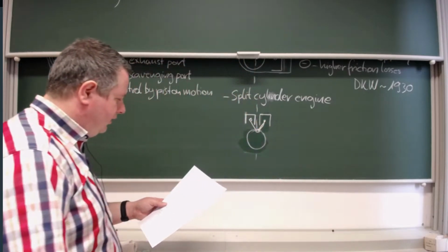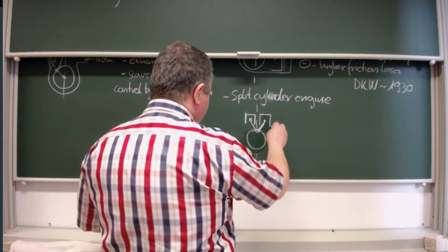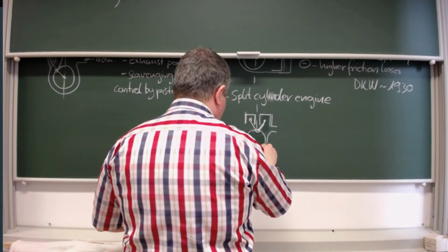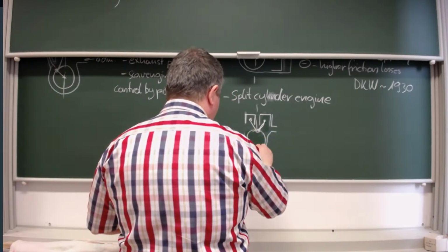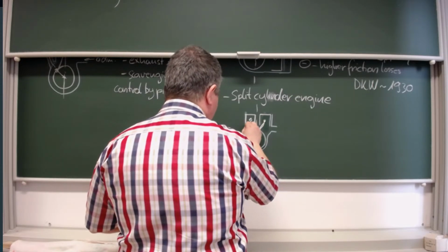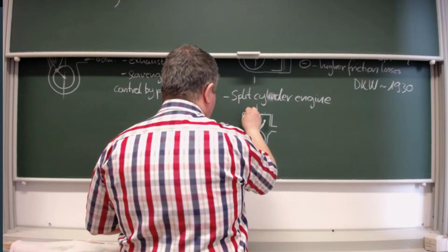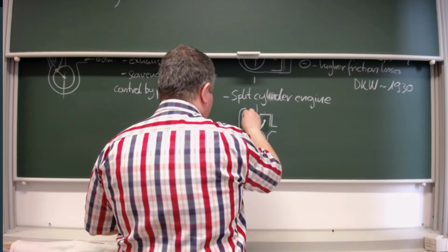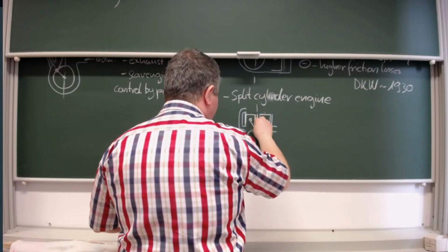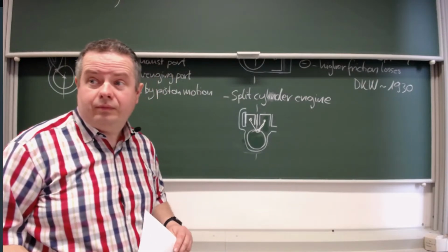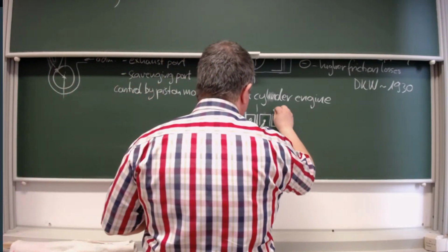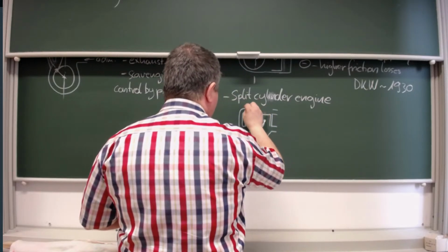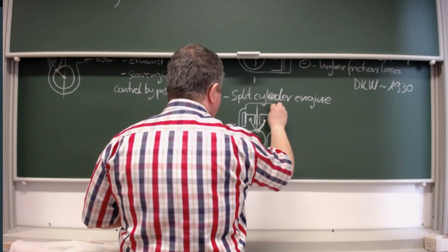And if I look at the cylinder, I will see the following. First piston, admission as usual, a large crankcase, then you get here a transfer port or scavenging port, you get the cylinder wall, and also a cylinder wall in the middle, plus you get exhaust here, and a cylinder wall till this level, plus a common combustion chamber.